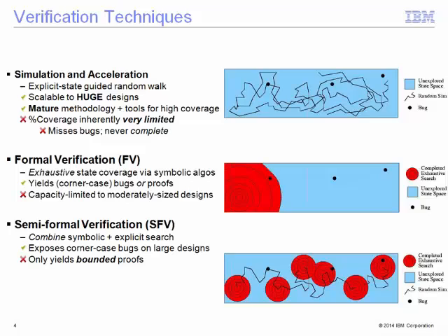This slide is very basic, and everybody knows this. Even today, the conventional method we use is simulation, and nothing completely replaces that with formal. People don't agree, and there are also limitations with formal, right? Why we go formal, we had enough stories from Kiran, and as Sudhakar mentioned, the Intel floating point bug and all that. It can cover conventional bugs. But apart from simulation and formal verification, what is also very important is semi-formal verification. The limitation of formal is that it cannot go much deeper.